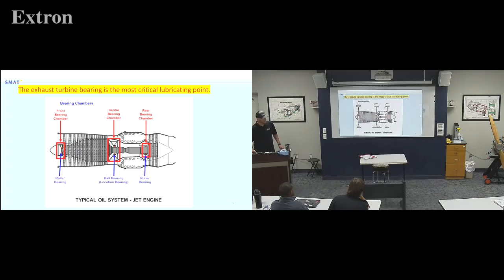Part of it ends up being, we're going to talk about it later, but a lot of the thrust force is actually not felt on the bearings. What you can get in your head, if you're like me, is you're picturing all those fan blades being the propeller that's pulling you through the air. Not exactly. You've got to think of it a little bit more like we've got a lot of material, you could say pressure, but it's going really fast. So we have a lot of energy coming out the back of our engine, going backwards, and for every action, there's an equal and opposite reaction. It's going to make us go forward.